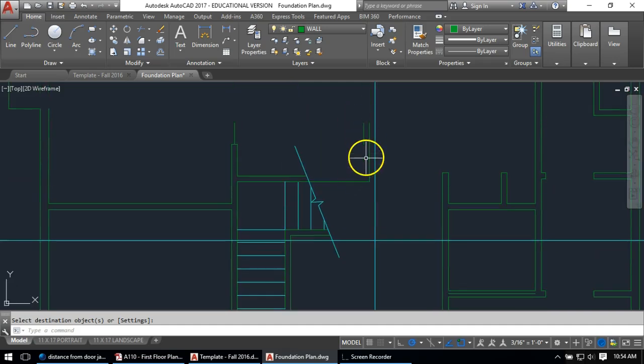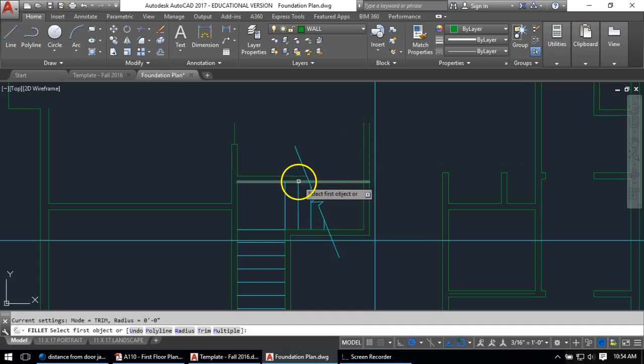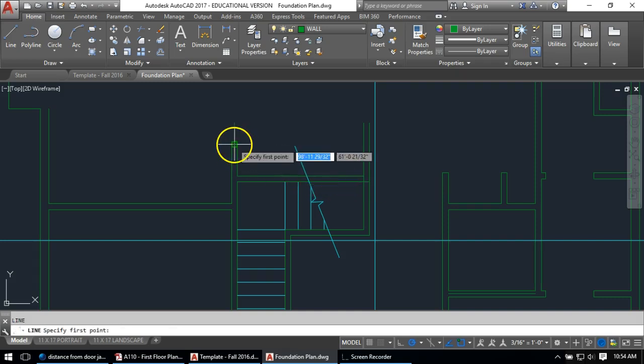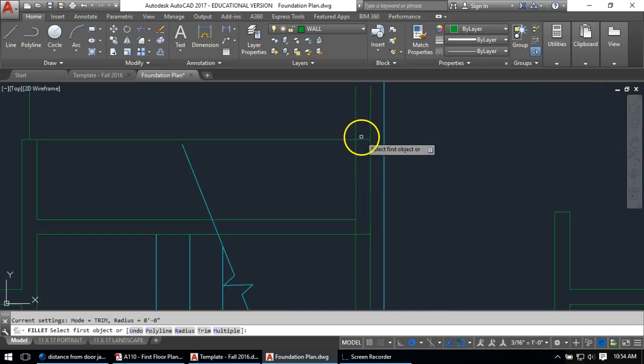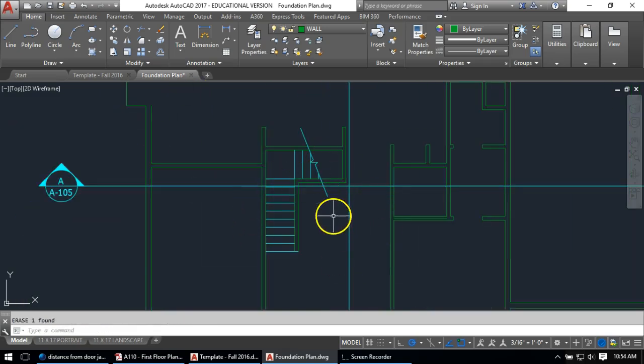Because this wall that I'm defining out here actually gets filleted all the way to this guy here and here. And then, once I have that, I can extend this guy out, and the top of the wall is in alignment at this point, so I'll draw a line over, fillet it together here, fillet it together there, and then do some trimming up as need be and erase that line right there. So there are the walls there.